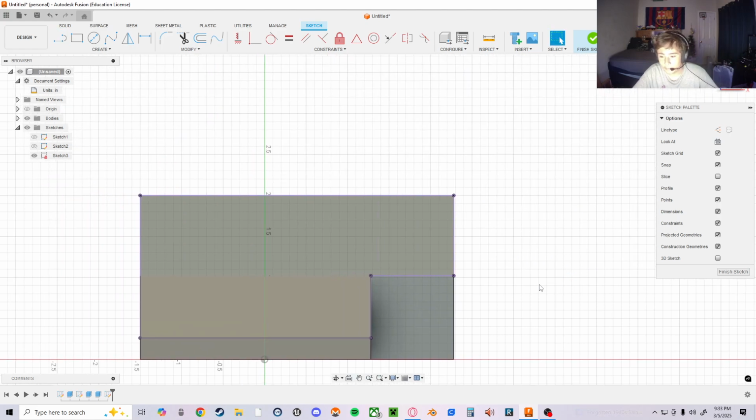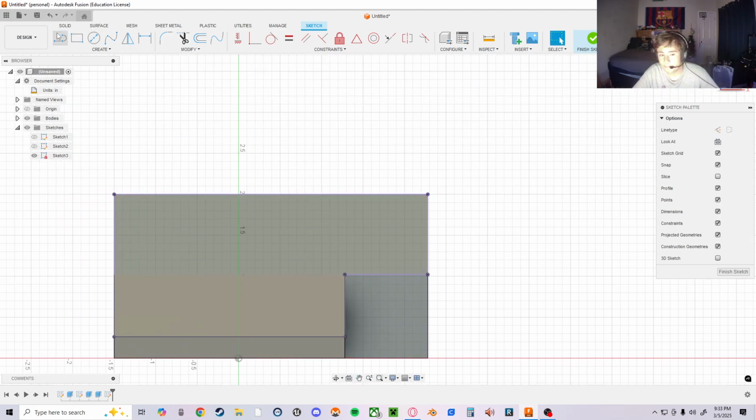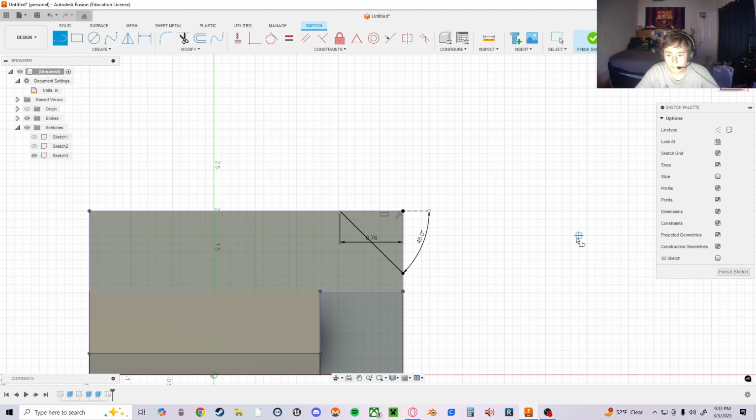I can get the midpoint too. Wow. Okay. Can we measure? I don't want to do this. Okay, 0.76. That's all we need to know for this. And then let's make this a construction line. From here, 0.76, it's going to cut downwards. And to regulate, we can just say a 45-degree angle. It's going to cut to here. And then go ahead and delete that.